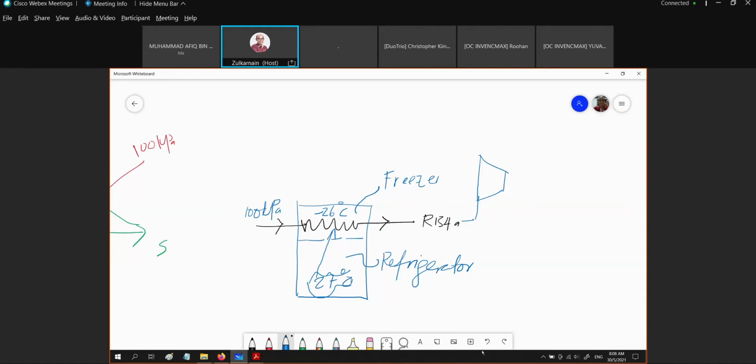Maybe we want to go to minus 80 degrees C. If you want to go that low, we have to create a vacuum in this line, in the refrigerant flow. We must create a vacuum kind of pressure, which is less than the atmospheric pressure. To get it, we put a compressor right here, and at the suction side we could have a pressure of less than 100 kPa. So this is a compressor.